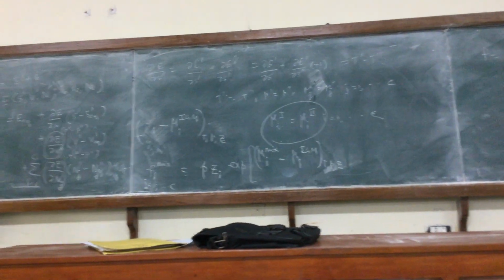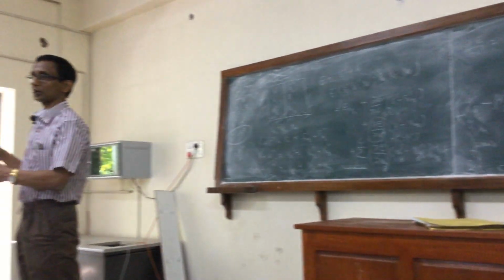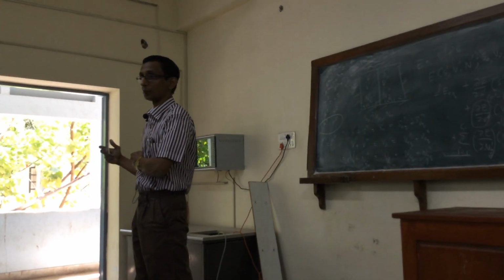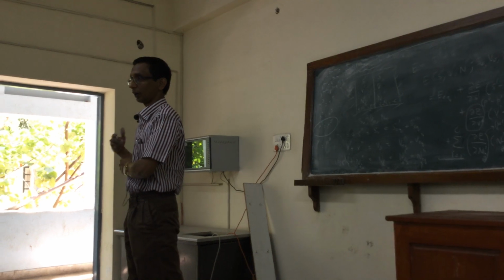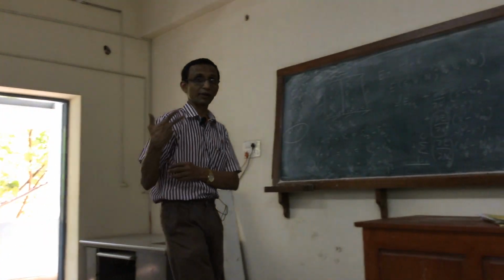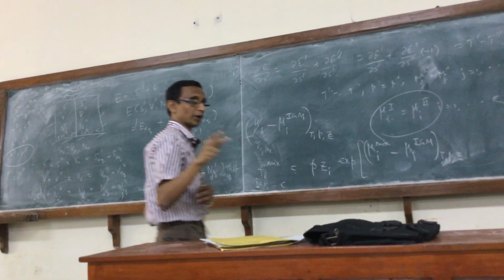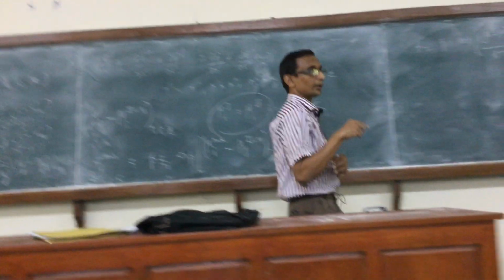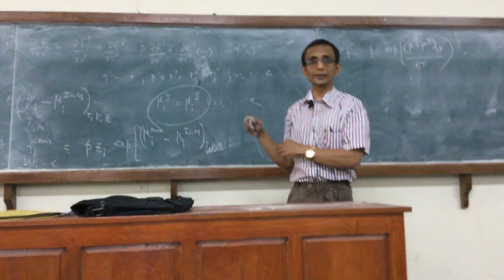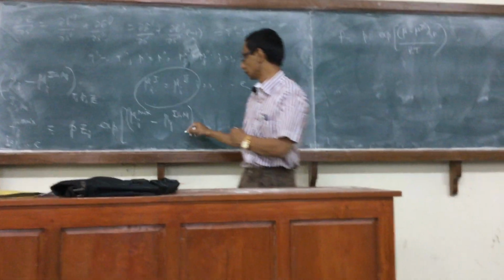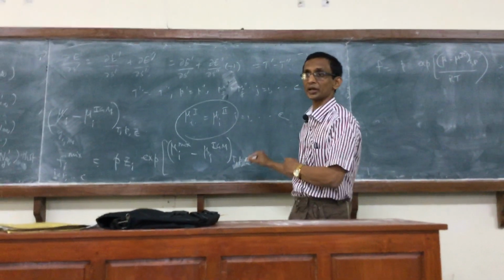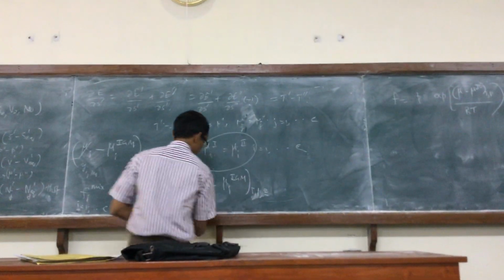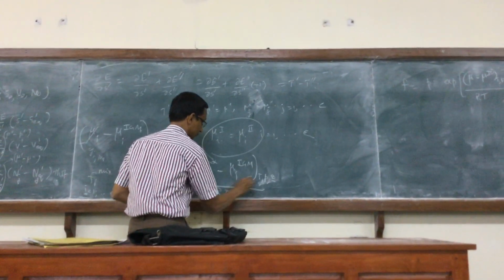Just as we saw for the pure component, you can also have a departure function at the same temperature and volume, and they are quite different for the chemical potential as well as the entropy and a couple of other quantities. So it is very important that the fugacity is always calculated at the specified temperature and pressure, with the chemical potential divided by RT.